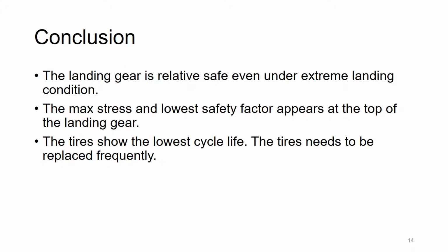So here's my conclusion. The landing gear is relatively safe even under the extreme landing condition, which has a pretty high vertical landing speed, and also the max stress and the lowest safety factor appear at the top of the landing gear, which is acceptable, and also the tires show the lowest cycle life, so the tires need to be replaced frequently.